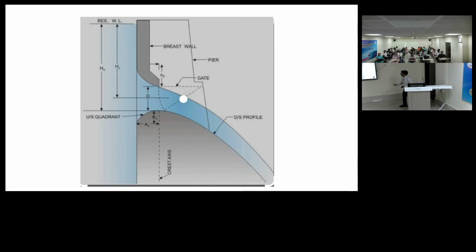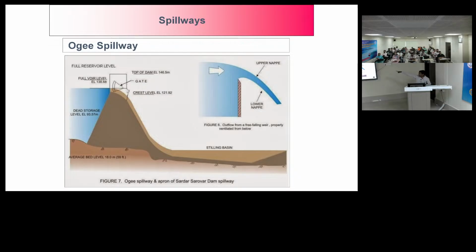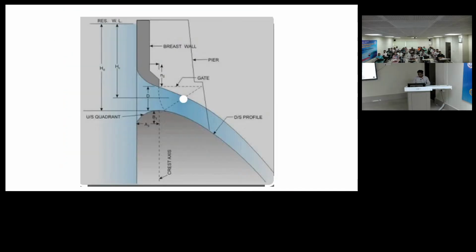Then to improve discharge further, these are photos of different dams, Parwan dam side photo. Earlier, in the previous image we saw the gate was at this place. Now we have reduced it; see, this is a sluice spillway. So we have taken the gate further down. What is the benefit from this? In this image you can see the gate was at the higher level, whereas here the gate is at the lower level. So why have we considered this option? Any other reason? Sediment also, we can remove very easily from this.